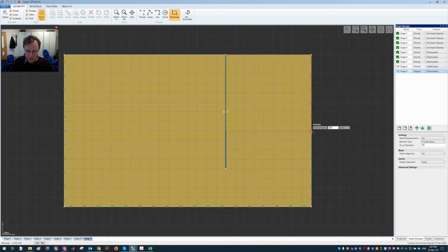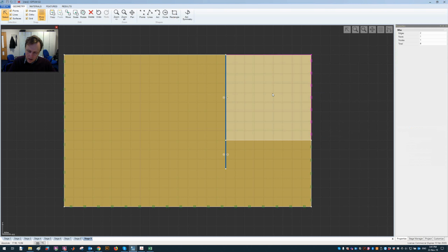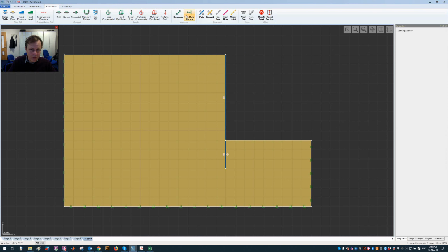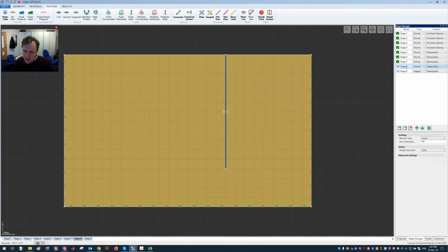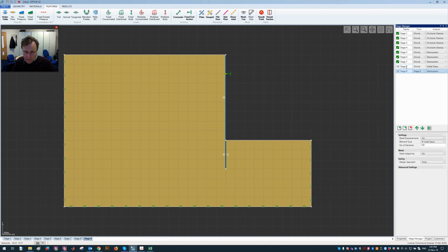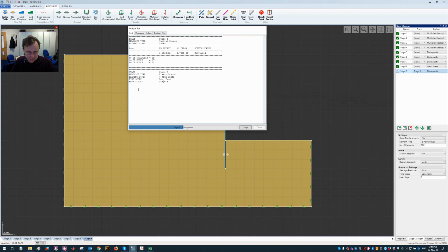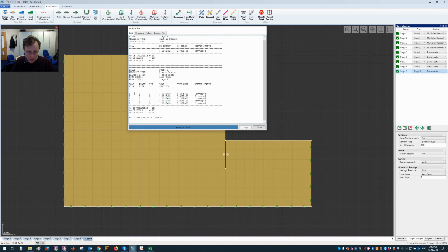And I'm going to excavate a huge amount of material. Let's try something like that. For that, I'm pretty sure I'll have to put in a fixed end anchor. So starting from the initial stresses, I remove this material and insert an anchor at the same time. And the question is then, what should the number of load steps be for this operation? The answer is that the number of load steps should be 1. There's really nothing gained from increasing this number of load steps to anything above 1.